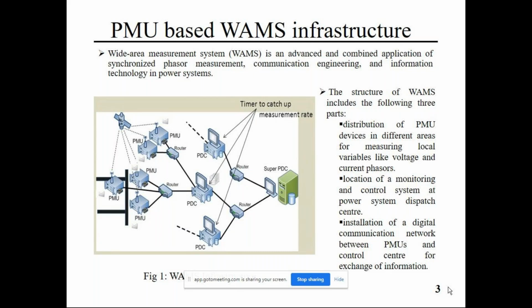So for that, that is again another domain, as I told you in the past slide, that domain I am not discussing here. But my focus is that you have to deploy the PMU. Now the question is whether the PMU cost is okay. The communication infrastructure cost has tremendously decreased. That is fine. And you have to obtain the phasor measurement. That means you are obtaining the phasors. For instance, the DFT block is there, and you are getting the fundamental phasor, which carries the relevant information for a decisive action.